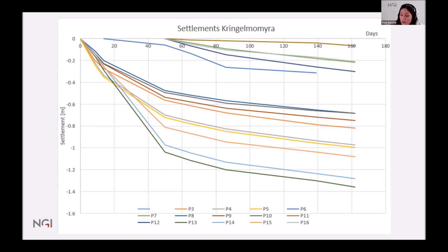They're measuring from 1.5 meters of fill, and the curve starting at 50, they are measuring from the top of the fill. So when the surcharge fill is in place, they're measuring on top of the embankment.